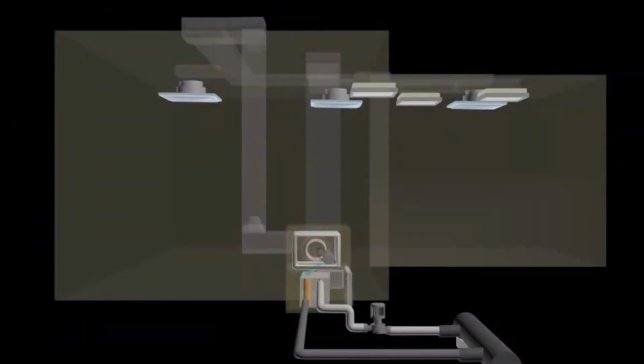For the airflow system, it is operated using an auxiliary fan which creates the air cycle from the room and mixes it with fresh air from the outside to the air handling unit and returns back to the room. The type of fan used was a centrifugal fan, powered by a motor and connected through a belting.